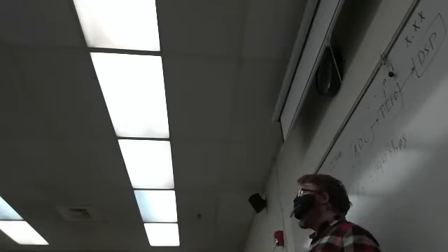I'm processing that at a rate of 24 kilobits per second. So the rate at which my FIFO is filling is the difference between those two. So R is equal to 144, it's filling up, minus 24.